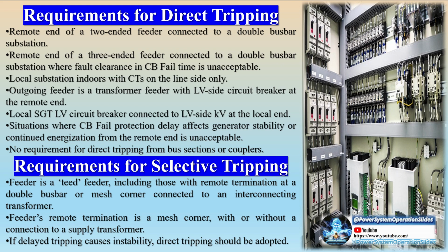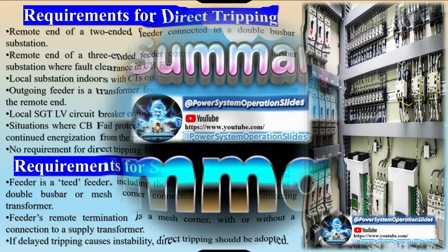fault. The directional element selects one of the currents as a reference and calculates the phase angles of the other currents relative to this reference. The element declares an internal fault only if all currents are substantially in phase, thereby supervising the normal differential element.